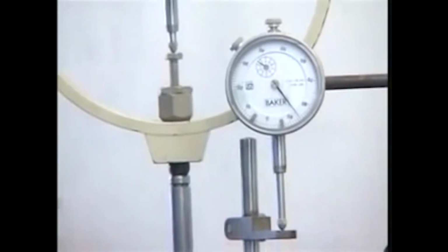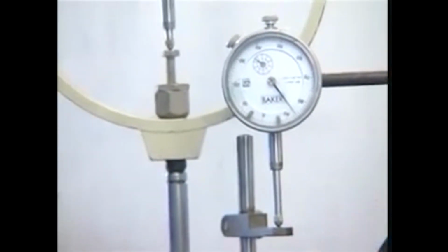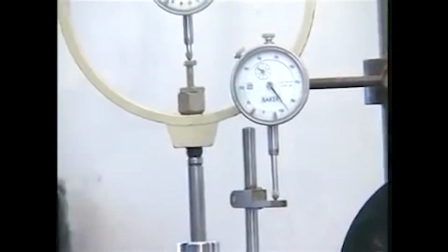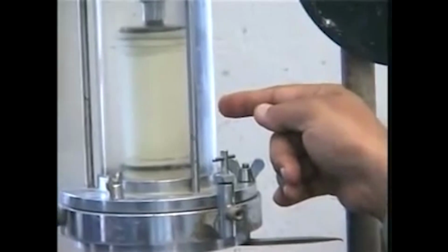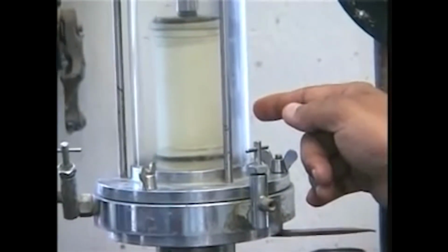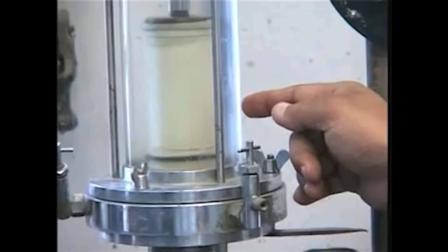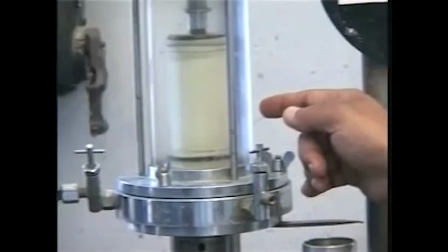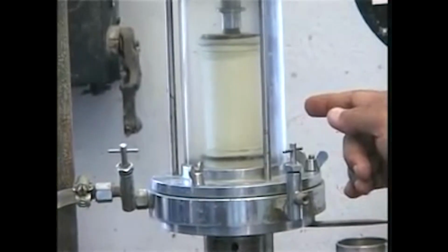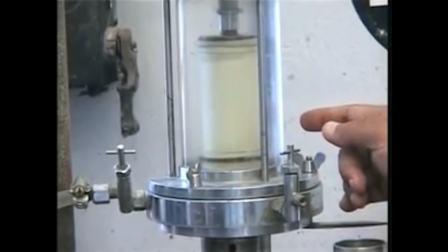We make use of this particular dial gauge for finding out what is the actual displacement of this particular triaxial setup. And we also have another connection from the bottom of the cell, and that connects to a pressure gauge. As you can see here, this allows us to keep track of the pressure in the water inside the triaxial cell, and we can pressurize the water to our required level using a compressor which is further to the left of this particular setup.